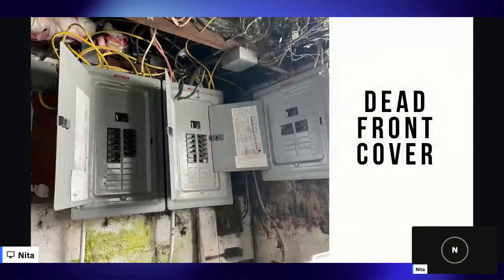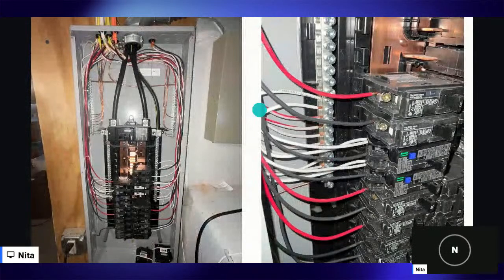So here, this is what I'm talking about. So you could look on this label and see the circuit breakers are numbered. This breaker number 7 serves for the dryer, whatever the case may be. Your breakers should always match the same type, should match the manufacturer of the box.